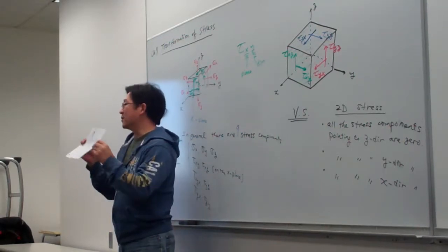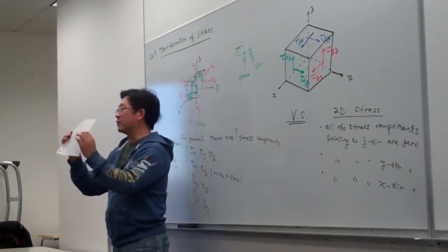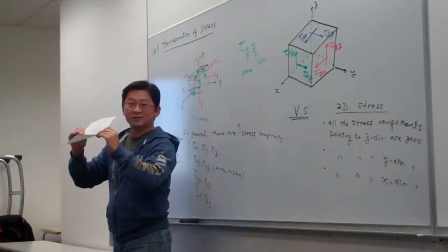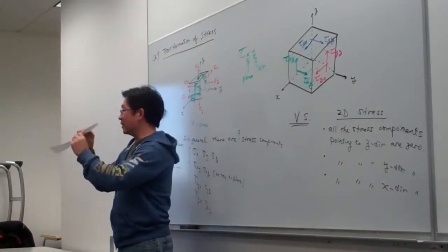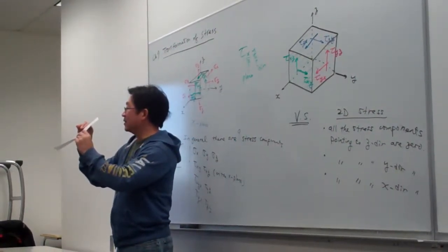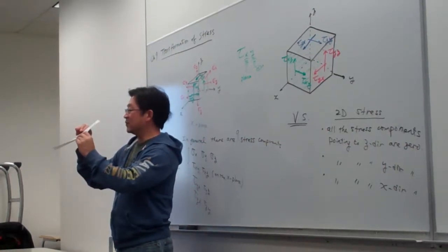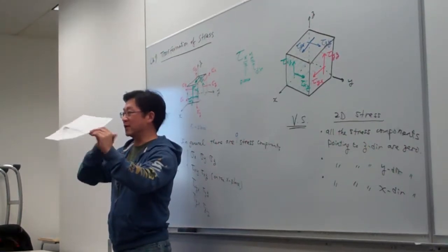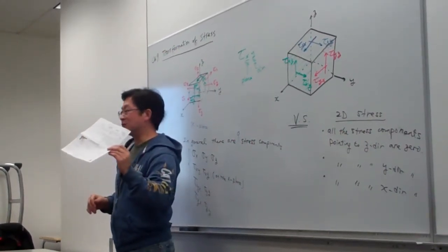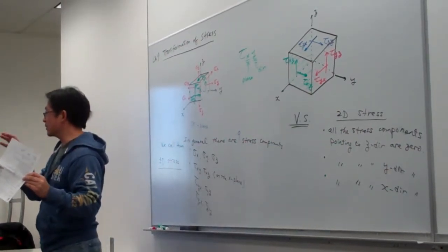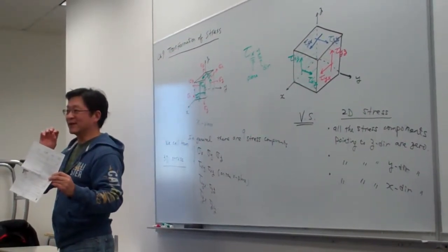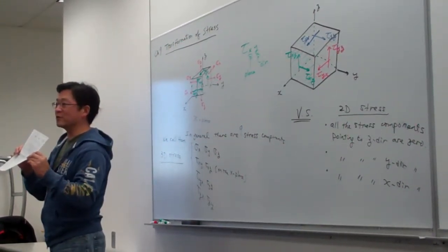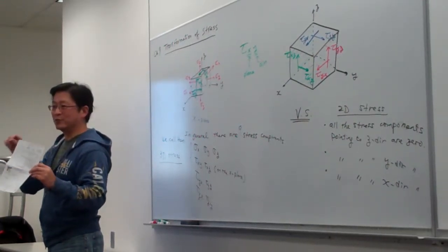Now if you imagine this is a membrane, and I apply loading in two dimensions, in this and also in this simultaneously, then in theory there shouldn't be any stress in this direction. All the stresses will be in plane. Like when you blow a chewing gum bubble, eventually it blows up because the material properties won't be able to hold the pressure you keep pushing in.